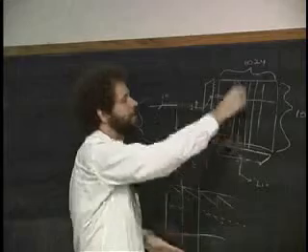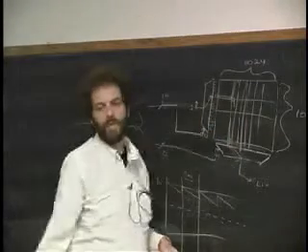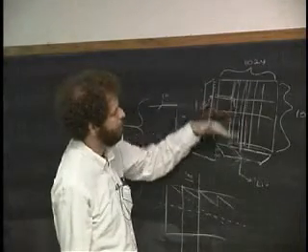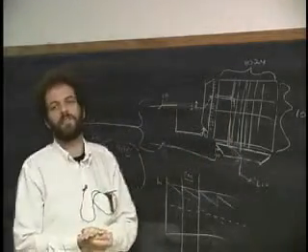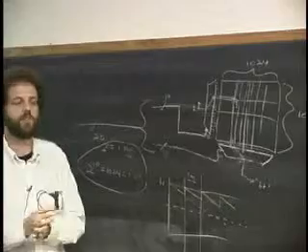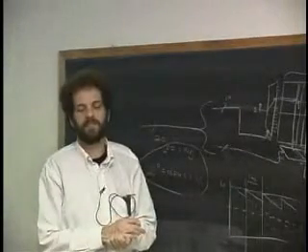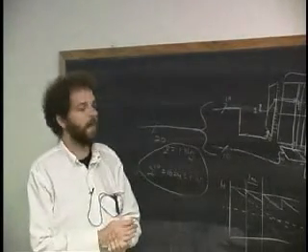Sometimes the distance is too far. They break the chip up into four halves. They have amplifiers here, here, here, and here, in lots of different places. There are all sorts of tricks that they do to try to allow all the capacitors to act as if they're the same size. Yes, it is a hard thing to do.